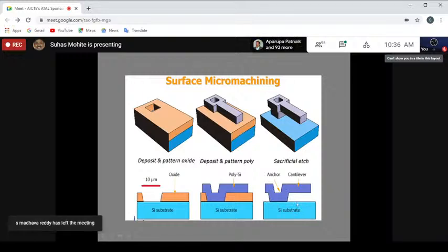If you have an electrode here, then this will be a parallel plate capacitor. And when a parallel plate capacitor is subject to displacement of one of its plates, such as the diaphragm or cantilever upper plate, there will be a gap change, and this gap change will create a change in capacitance, and an electrical signal will be available. Or you can deposit materials such as piezoelectric or piezoresistive film on this, and that can also give rise to a signal when it is subjected to mechanical deformation.